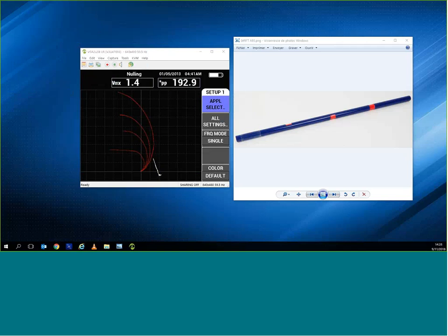So null the defect-free zone. We're going to scan our tube. So there we go, and that's 360. We're going to press freeze because we have all the functionalities that the NORTEC can use. And we're just going to increase the gain till we have basically like that. Maybe move it over here. Bring it down a bit. So now we have our calibration is complete.